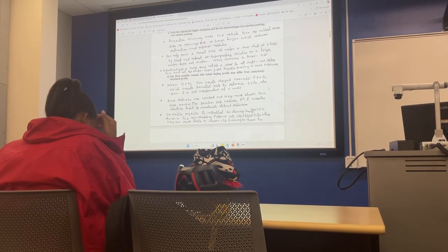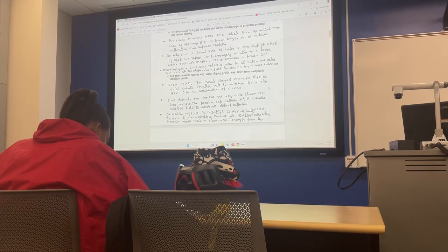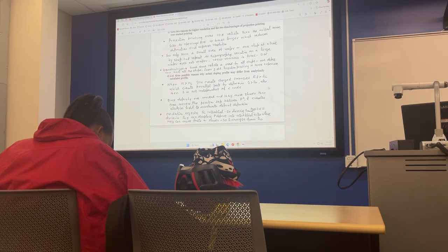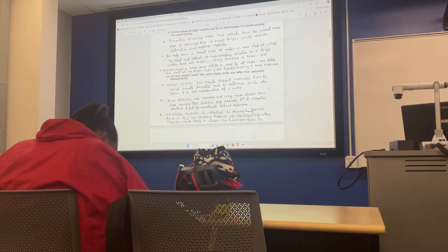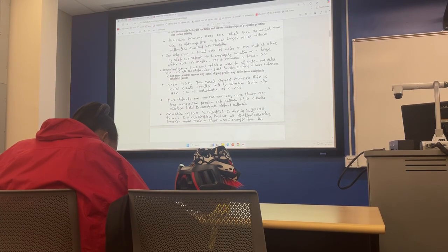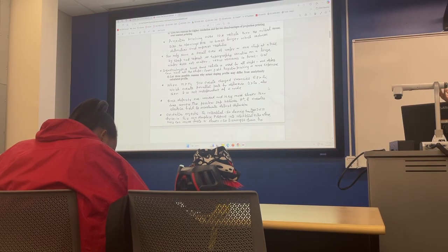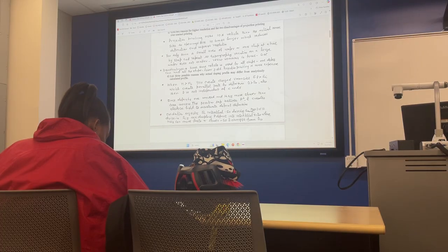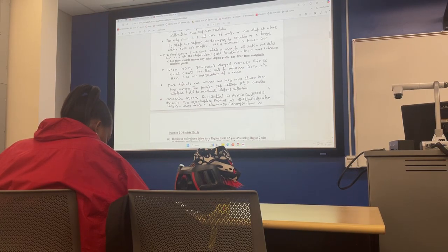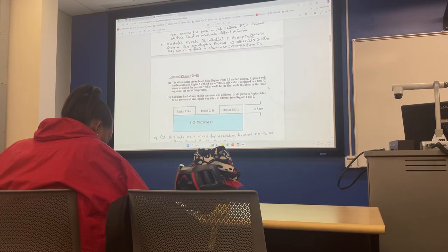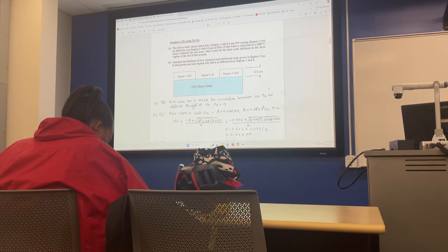Okay, then oxidation was very simple: the H2O molecule moves much faster through the oxide, and solubility is higher. So you got more to start with, which is solubility, and faster movement. So obviously you will have a faster growth rate with H2O. Okay, so that was problem number 1.